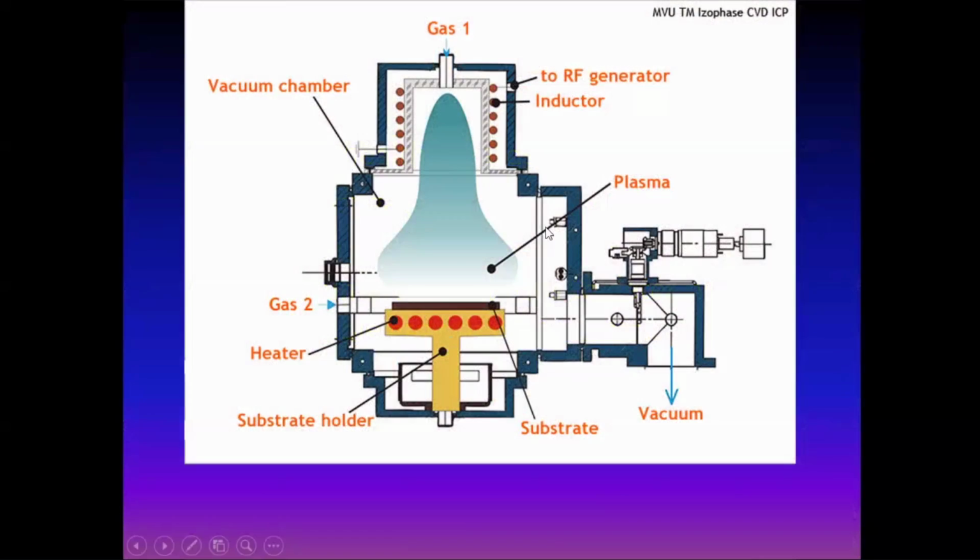So this is the machine layout of a CVD machine. If you can see, this part consists of the vacuum units. For creating the vacuum in this assembly, this whole chamber is where you have to create a vacuum. So you will be having 3 pumps, 3 gauges. Gauges are used for measuring the vacuum, and pumps are used for creating the vacuum.